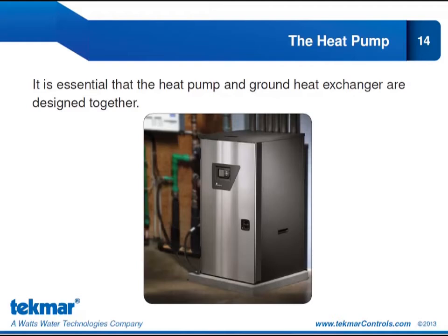It's essential that the heat pump and the ground heat exchanger are designed together. So the design and selection of each of these components depends on the other. The sizing of the loop is based on the capacity of the heat pump, and the efficiency of the heat pump is a function of the water temperature produced by the ground loop.